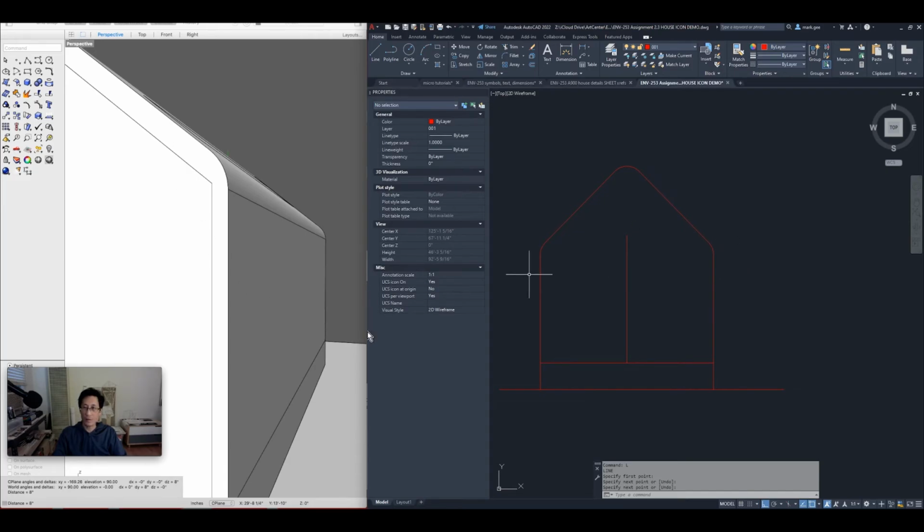lines here, I'll just use the offset command. I'll use that twice with two different offset distances. So we'll do offset. And you can see that it's kept the setting for 8 inches already. So that is what I want for one of them. So I'll just hit enter to accept it. And the one that I do want at 8 inches is this one. So we'll offset that 8 inches. Okay. And like I said, we'll do it twice.